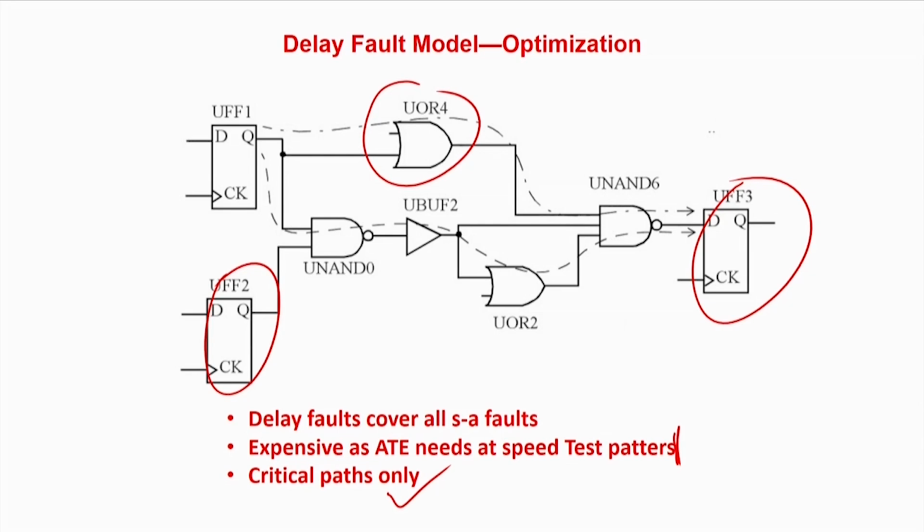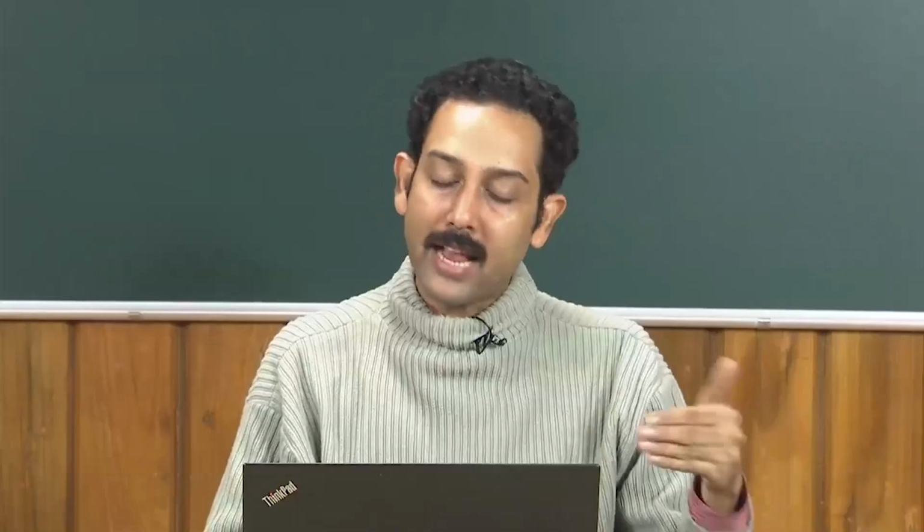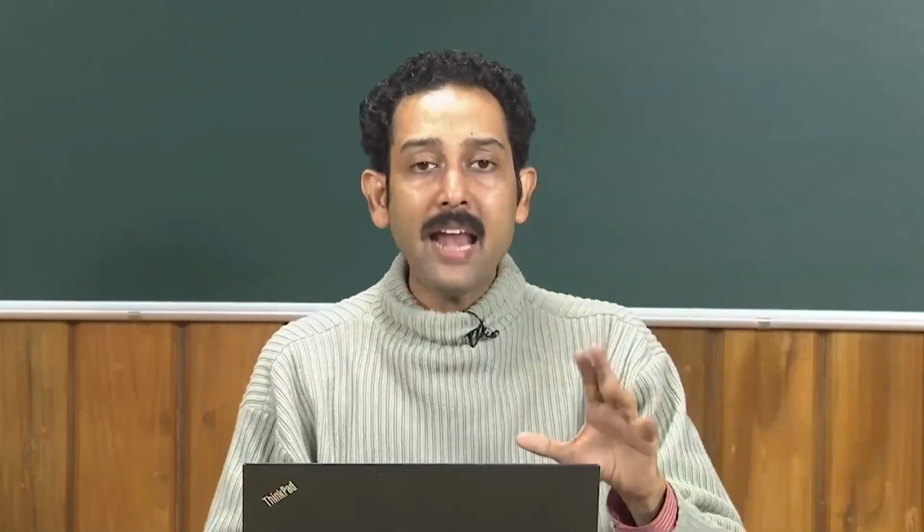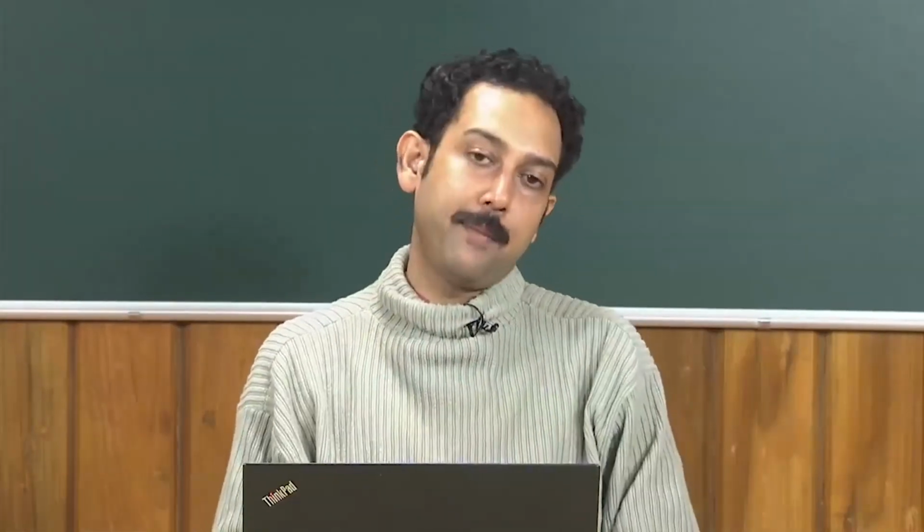So what have we seen in this? We have seen that advanced fault models are very much required if you are going for testing of circuits at the deep submicron level, which is the de facto standard of fabrication for NoCs and SoCs. Interestingly, if you go for testing of the advanced fault models, automatically some stuck-at faults will be tested. What remains to be done, you go for at a later phase, so that you reach 100% coverage.